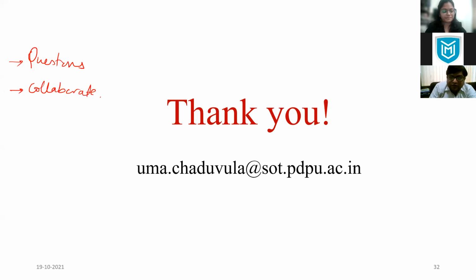Okay, madam, it was a really nice presentation, very lucid, I must say. So the very first question is from Professor B. A. Mir, and he wants to know that expansive soil is highly compressible with MDD around 12.5 kilonewton per meter cube, but UCS is 200 kilopascal. So the UCS seems too high and mismatching with this index property. What is your comment?